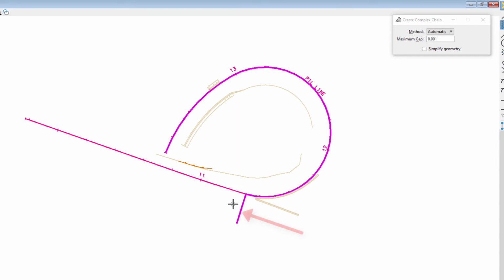So when I hit the reset on my mouse, the right button, watch the color change. You notice that it unhighlights that segment and it goes to the other element, which happens to be an arc. Now I need to accept it to say that is the path I want you to go. So I do another data, accepting that. It now has highlighted everything that I want. I would do an additional data, left click, to accept it.